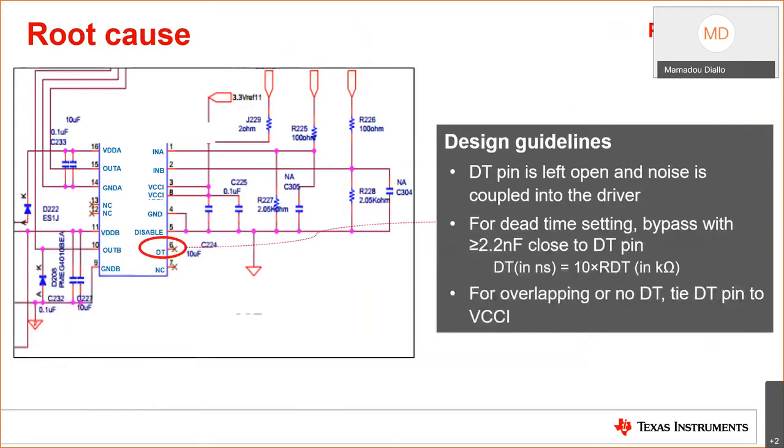So typically, we recommend essentially not leaving any functional pins floating, which may cause noise coupling into the driver IC. The specific case shows the dead time pin left floating when it should be either tied to an external resistor for dead time setting or tied to VCC to allow overlap of the 2 channels. The functional pins should never be left floating when unused, including input pins, which should be tied to ground when that specific channel is not in use.